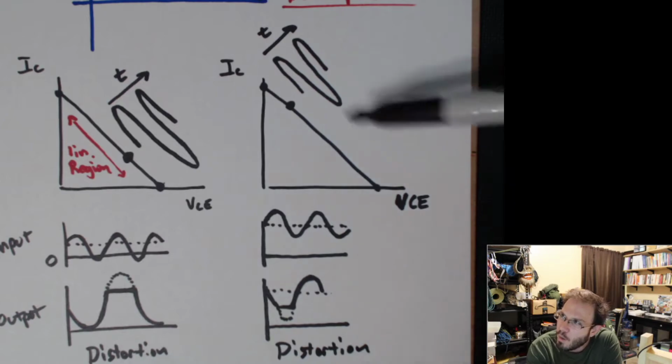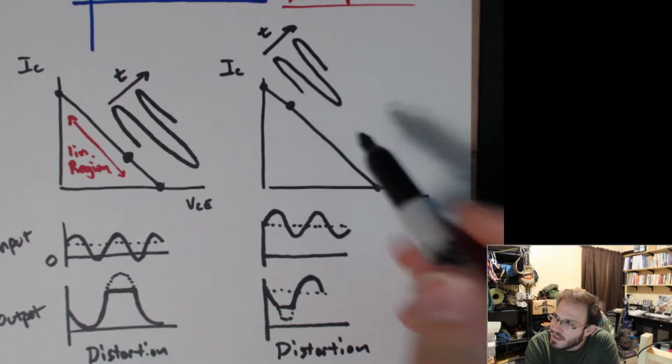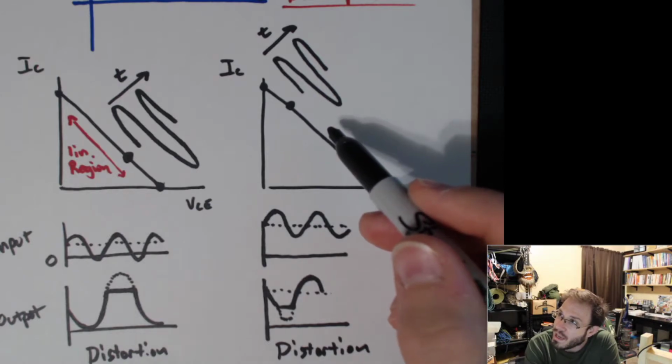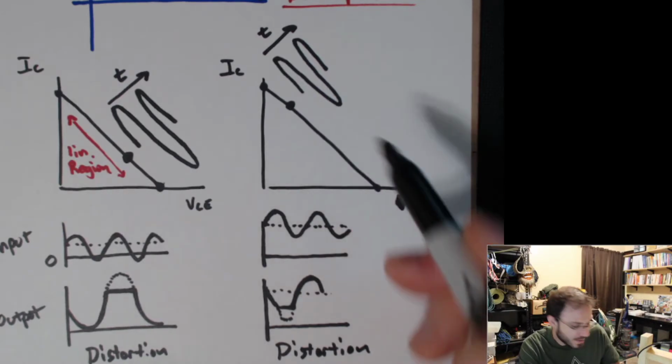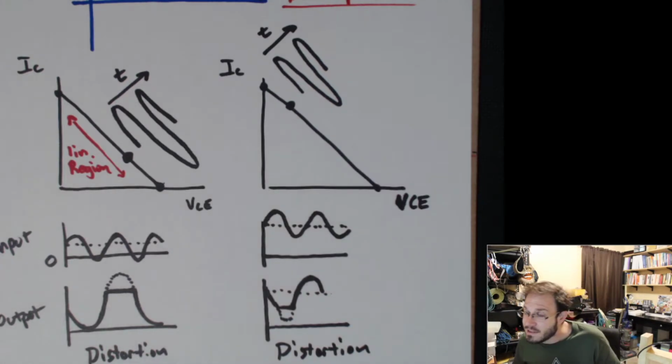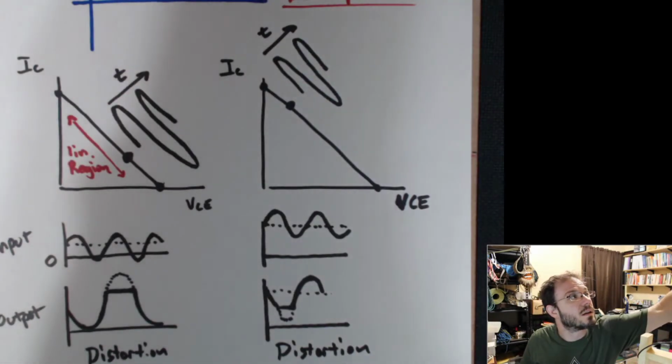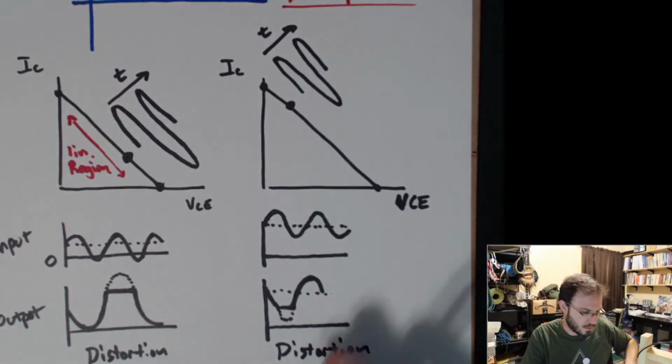Okay? So for this reason, it's nice to see the load line and ensure that we are at its optimal place. So for the case of designing an amplifier, there's an optimal position for this Q point. So if you want nasty distortion for your electric guitar, make the crappiest amp possible. Yes. Okay. That's exactly how it used to be done.